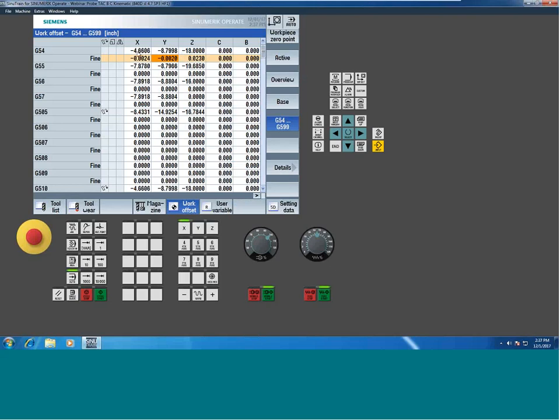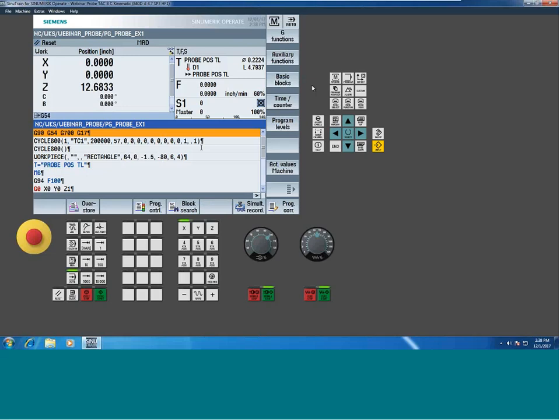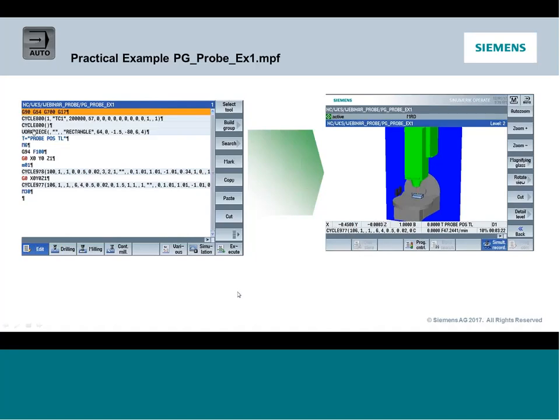So the fine offset keeps me from wiping out these first offsets. That's also handy maybe if I'm doing adjustments over the day because I'm getting some thermal expansion. But I know when I come in the next day and the machine's cooled down, I can just zero out the fine offset because I'm going to be a lot closer than I would be at the end of a work day. Okay, so with that being said, let us transition back to our slides and take a look at how we can start building off of these functions.